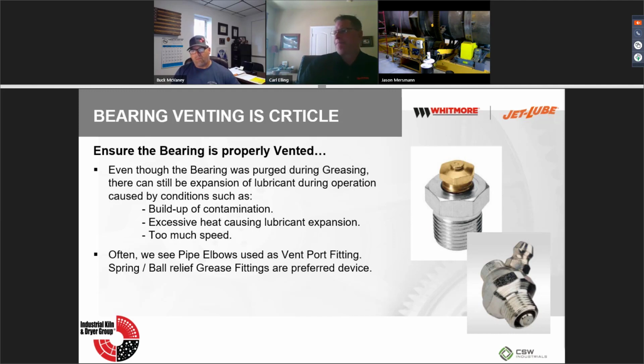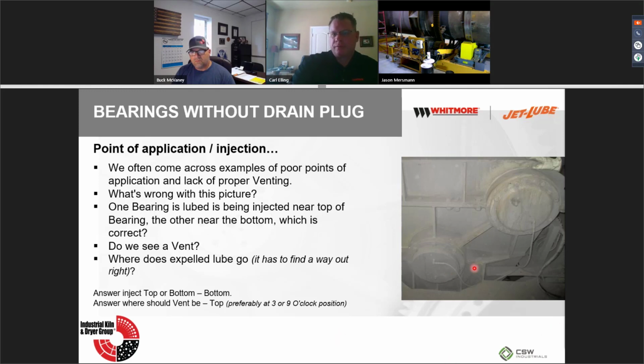Hey, Carl, also, yes. He followed up and said he was talking about the location of the Zerk. Okay, good deal. Let me go back. On this one, the Zerk here, your 270 degree would be the proper location. So what you're doing is you're putting the Zerk here, and then your vent will either be over here at 9 o'clock or at the 3 o'clock position. Once you start pumping grease up to this point, this is the level that you want to have grease applied. So once you start pumping in grease and you see grease coming out, either vent on this side or on this side, you can stop adding grease. And then it's properly level, and then we'll go into how frequently you need to replenish that grease later in the presentation.